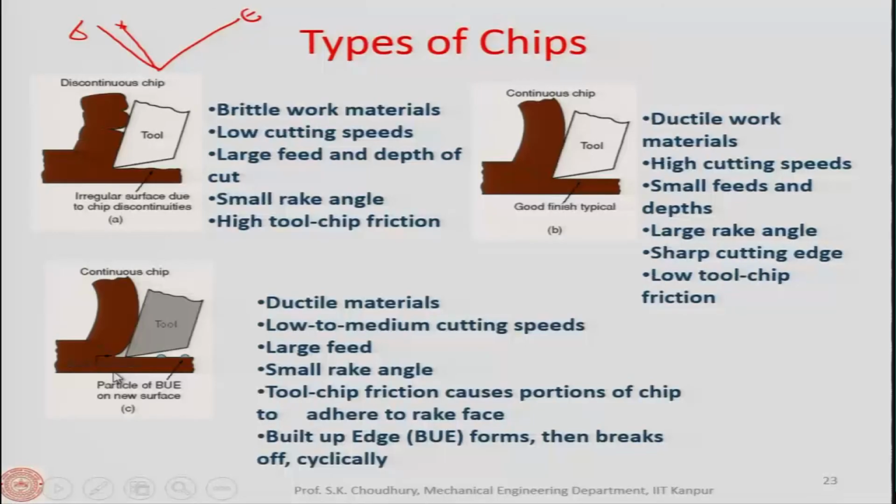So finally, if this is the tool, in front of the tool it will be piling up, I am exaggerating, like this. It will be piled up like this. This piling in front of the tool is called the built up edge. Now, when it is breaking, you can see that part of this will remain on the already worked surface, and part of it will be embedded in the chip and it will also be on the tool tip.